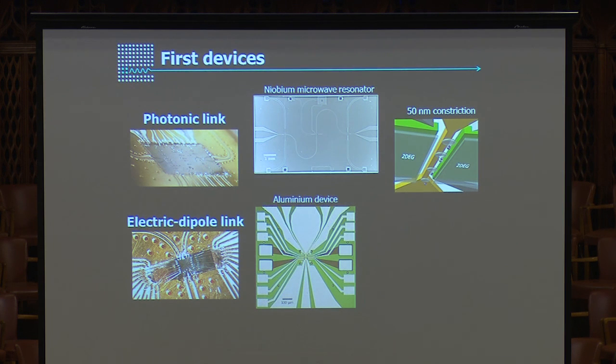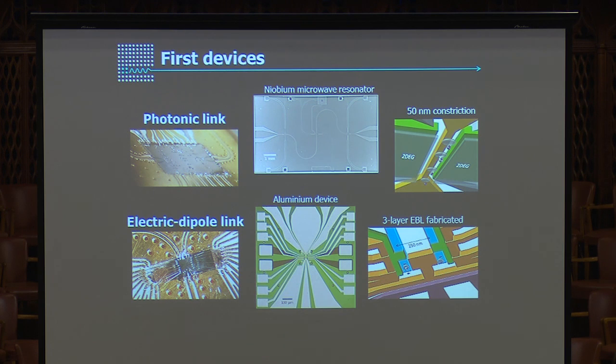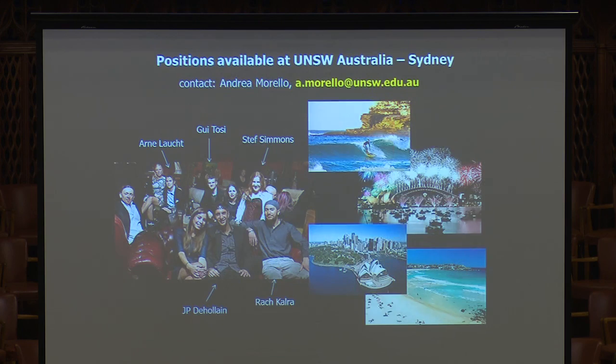This is the electric dipole device. It's basically two spin qubit devices face to face with a slightly modified gate layout. You can see here the magnetic drive line that gives the Raman field for the nucleus. And here are two coplanar waveguides that terminate in an open circuit to do the 40 gigahertz electric drive. These are all nicely impedance matched. This is done with a 3-layer overlapping gates technology that is also used in the silicon MOS DOS that Andrew was discussing yesterday. So we're very excited about this progress, and we hope to have some experimental data to show you next time we meet.